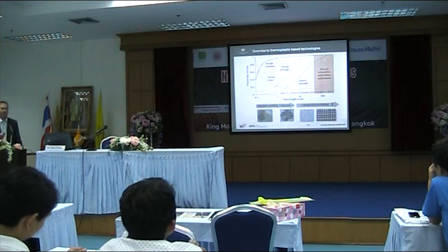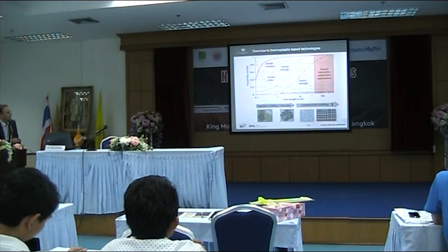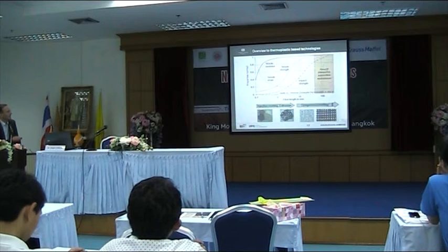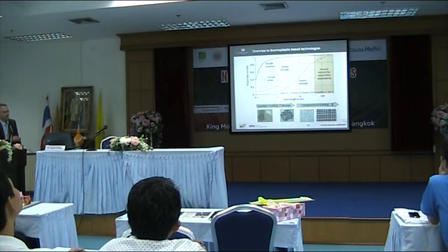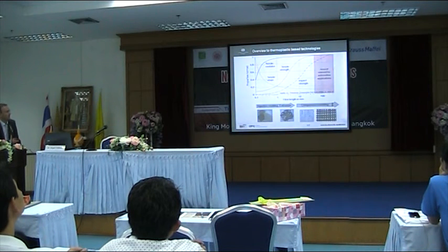So now when we look at the resulting properties in injection molding, we see that we cannot use endless fibers, we have fiber reduction and we have more or less random fiber orientation. Well, is this so terrible compared to compression molding? We can say, especially for tensile modulus, if the fiber length is around 1 millimeter, it has already reached a really good level.